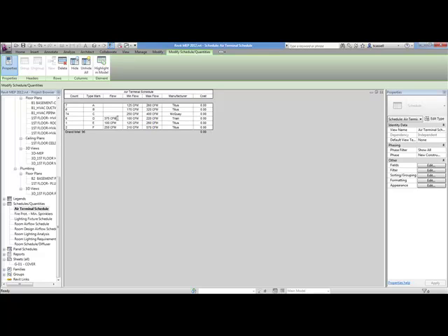So I can tell you that if I have an actual flow on 6 of these diffusers of 375 CFM, then I did not choose a diffuser that is the right size. These are going to have to be a different diffuser, such as a type F diffuser, in order to support that flow.